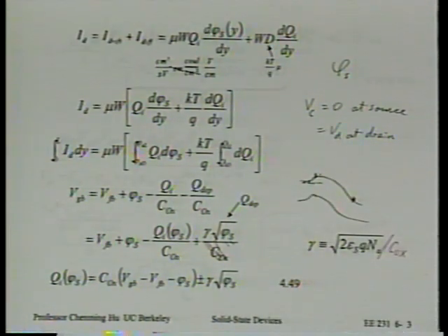So phi S is a little bit more detailed view, but if you first want to derive IV characteristics, if you don't have to come to the detailed view as phi S, if you can just view it as a resistive sheet, we'll take the second view. But here we're going to go back to that more detailed view, where there's a very clearly defined potential called phi S, which has to do with band bending. All right? Okay. So both are useful, and they don't contradict each other. They don't happen to be identical either. These two things are not identical.